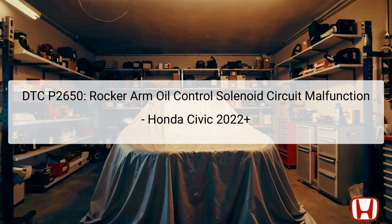The rocker arm oil control solenoid regulates the flow of oil to the rocker arm oil control valve, thus controlling variable valve timing. When the Honda's Powertrain Control Module, PCM, detects an output voltage outside the specified range for the rocker arm oil control solenoid, it triggers the P2650 code, indicating a potential malfunction in this system. It's essential to address this error promptly, as it might affect engine performance and efficiency significantly.